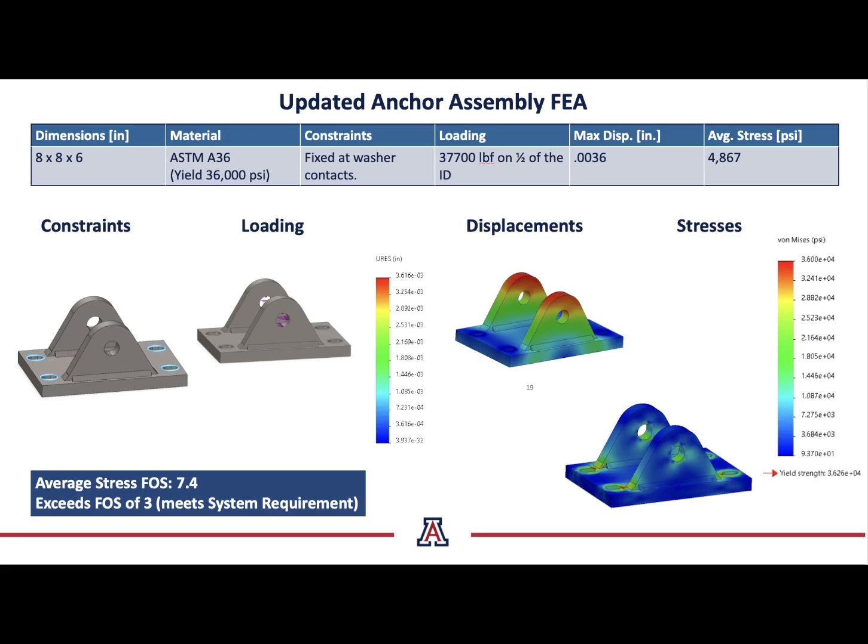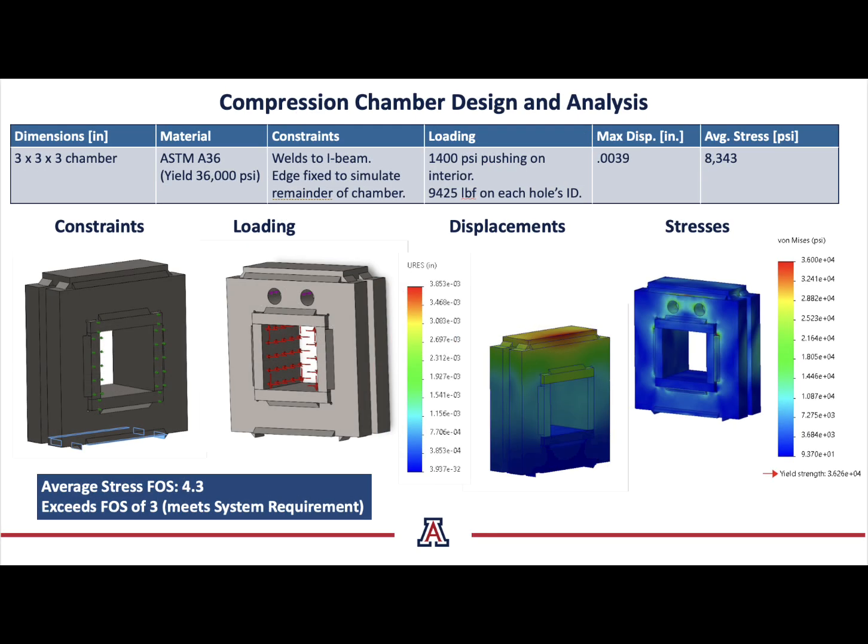We also analyzed the anchor assembly, which is responsible for transferring loads into the frame. The results showed a strong distribution of stress with minimal deformation, again meeting our safety requirements. For the compression chamber, we simulated internal pressures during operation. The analysis confirmed that the chamber can withstand the applied loads while maintaining structural integrity and consistent geometry.